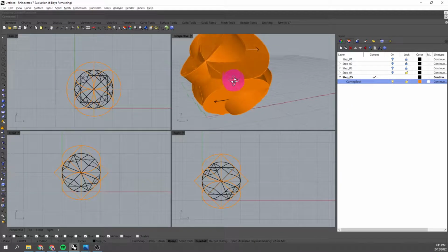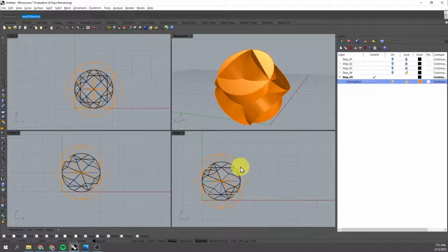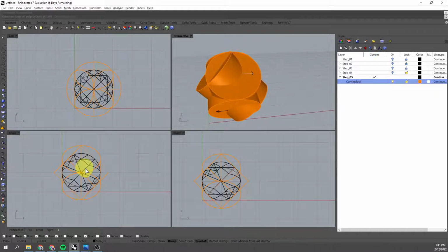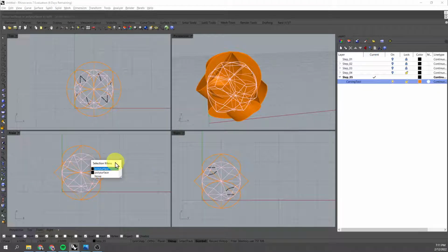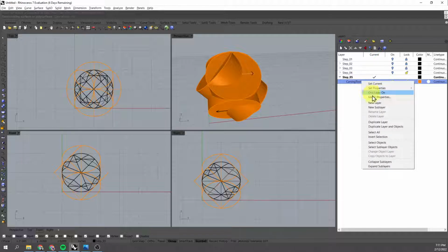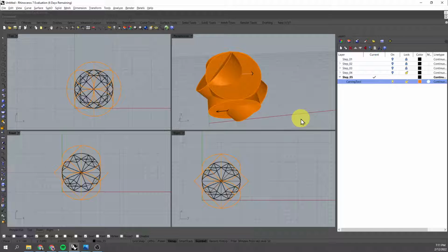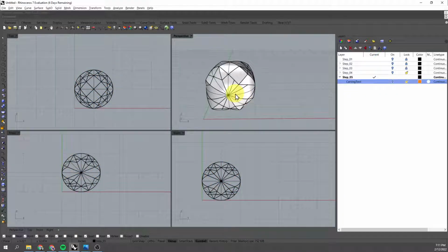All right. So let's go ahead and run our Boolean command. Boolean split. If you cannot see the object from here, you can select it from any of the other windows. So I selected my poly surface, and I'm cutting with everything else. So let's right click on carving tool, select objects, enter. Alright, let's turn this off. Let's see what we're left with.